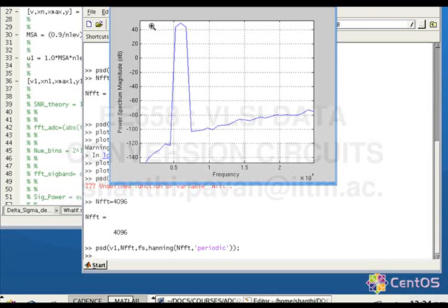No, okay, forget about this. So I gave you the output waveform of the delta sigma, right? It's basically a sine wave with some shaped quantization noise. What do you want to do next? You want to figure out if your delta sigma is working properly or not. So what you want to do is to actually measure the in band signal to quantization noise ratio, just like how we did for a Nyquist converter.